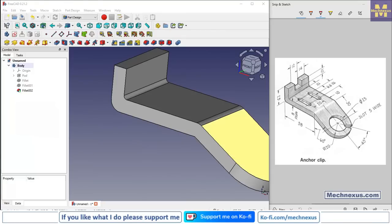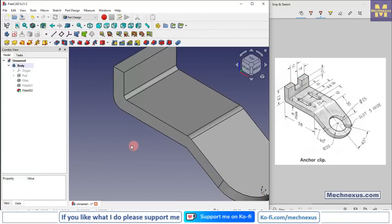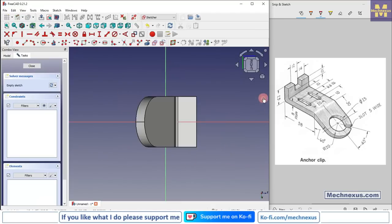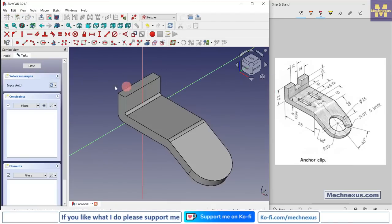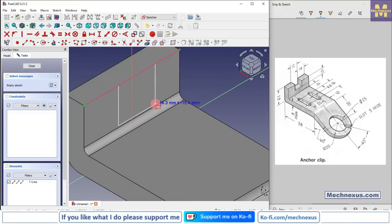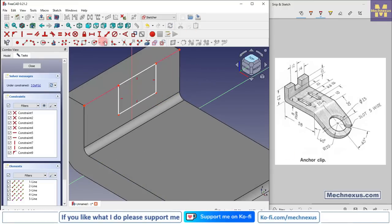And now we will create this cut. So we will press 0 for isometric, select a face and click on the sketch. Switch to the isometric and click on the project geometry, and here we will select rectangle, and we will use the symmetricity.